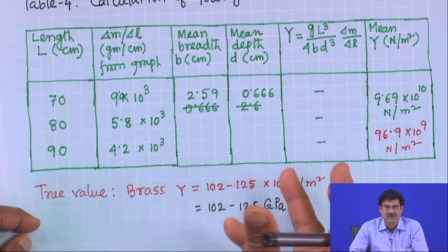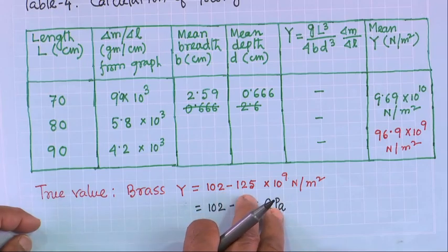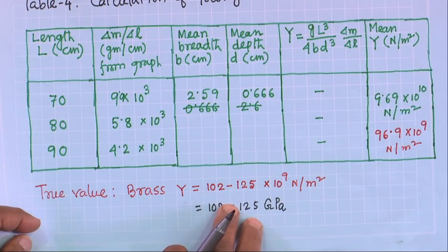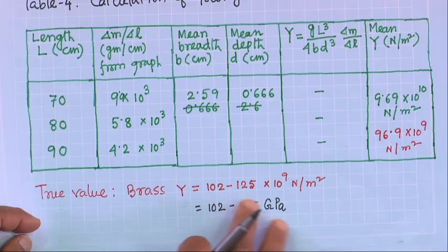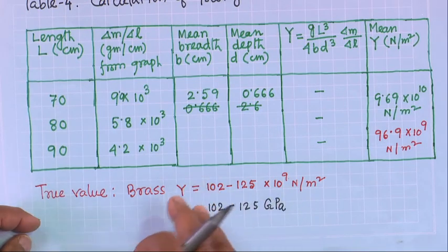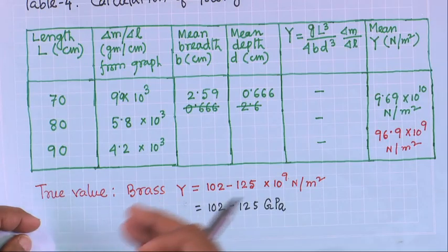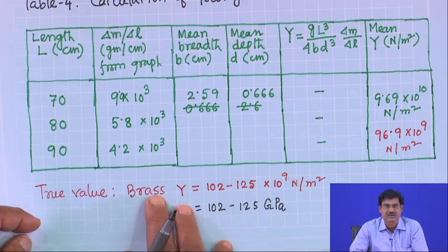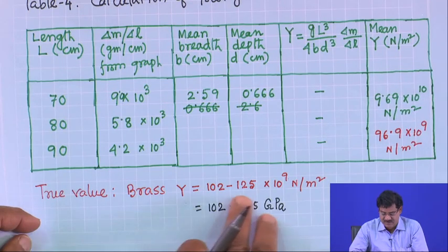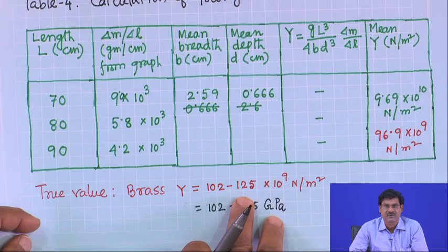I think zinc, copper, etc. are there. In which percentage they are there depends, because the mixture is an alloy of 2-3 materials. So, depending on the percentage of each individual pure material, it will have a different value. So, one has scope to adjust the composition in brass. If you want a higher Young modulus, you can choose your composition such that it goes towards this value, 125.